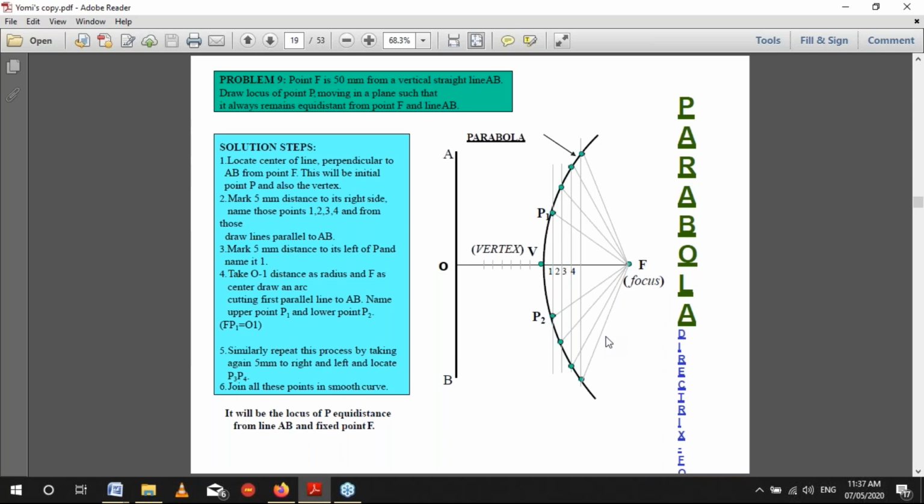Now, generating a parabola, the tangent method. You can see how it is done on slide 23. You draw the base RS, which is equal to 70 millimeters, through R and S. Draw lines at 60 degrees to the base, meeting at L. Then divide RL and SL into the same number of equal parts, that is 6. The divisions are 1, 2, 3, and 1 prime, 2 prime, as shown on slide 23. Join 1 to 1 prime, join 2 to 2 prime, and so on.